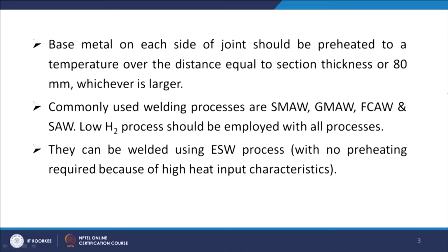Now, they can be welded using the ESW process, that is electroslag welding. In that case we do not require the preheating because of the high heat input characteristic of the ESW process. So, in this way you will have certainly some difference as compared to the mild steel in these processes.